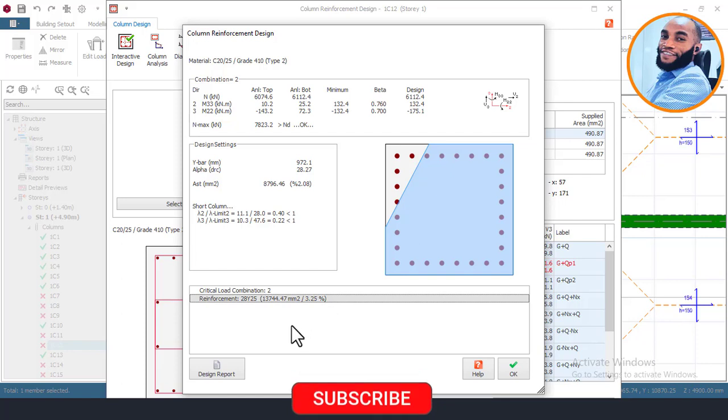Okay, so right now you can see that what it's showing is that it used a critical loading combination of 2, which is the maximum actually on this column to design for that, and then you can see that the reinforcement which is now produced for the column is 28 numbers of Y25. So once you are able to see your reinforcement without any warning again, then that column is okay.